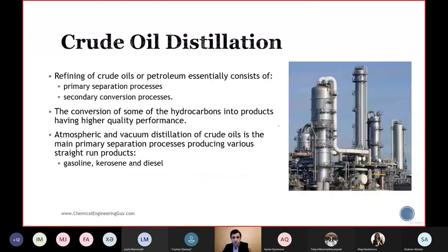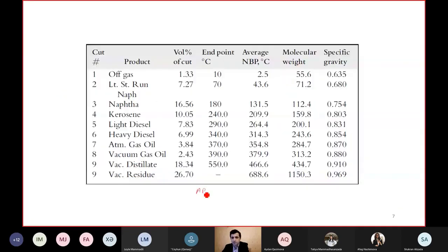So atmospheric residue has a specific gravity of 0.9. You are right that it is hard to move the atmospheric residue or higher density products in the pipelines, but we also have to consider that they have a temperature of around 400 degrees Celsius or even more. So when the temperature is higher, this helps lower viscosity. With lower viscosity, we can easily move them in the pipelines.